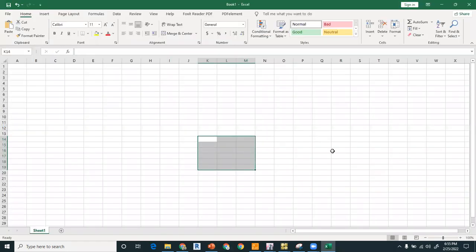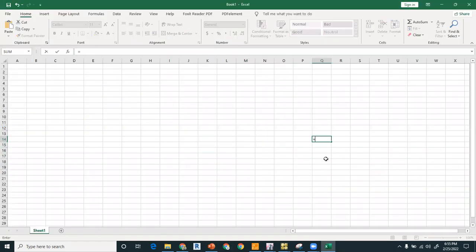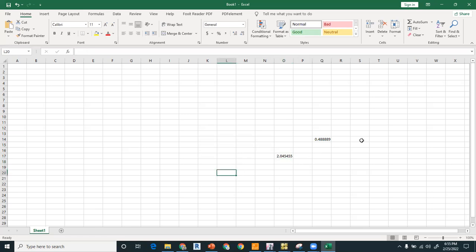So now you can use the bars. For example, if I use number 4, number 6 bar, and if I divide 0.9 by 0.44, it comes out to be 2 bars. So you have to go for the 3 bars because it is slightly greater than 2. You can also go for the combination with the 2 number 6 bar and 1 number 4 bar, right? So we will be using 2 number 6 bar and 1 number 4 bar, so it will fulfill the requirement of the beam.